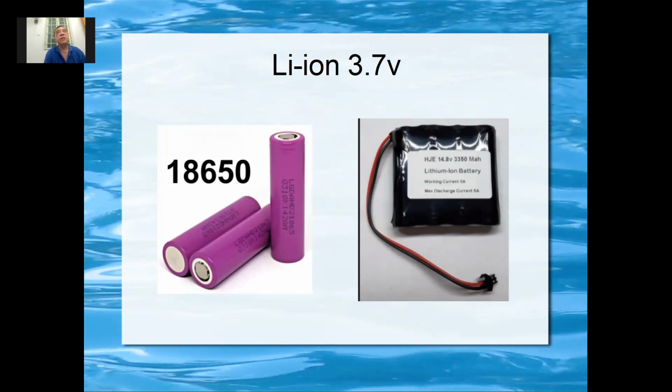When one battery is full, the other battery is not full, then you get into problems. The one that is full, if you continue to charge, you can damage the battery. Then the one that is not full cannot be charged. So you need a balancer, where the electronics will bypass the battery that is already fully charged, and then go on to charge the subsequent ones. So the electronics will control.